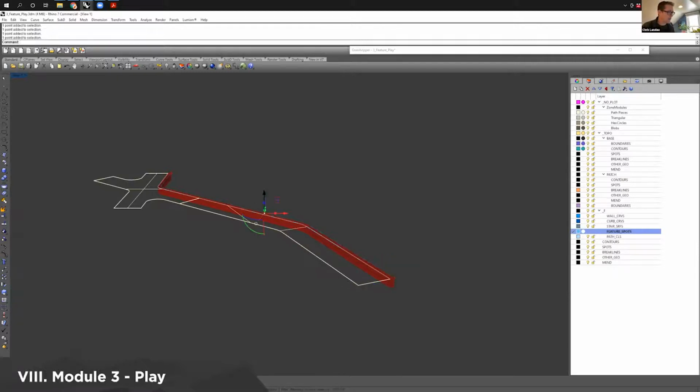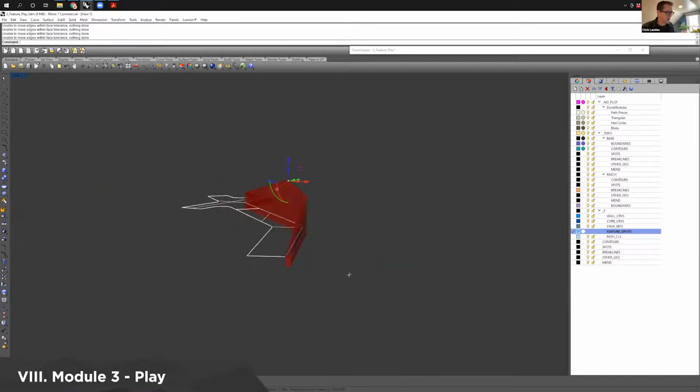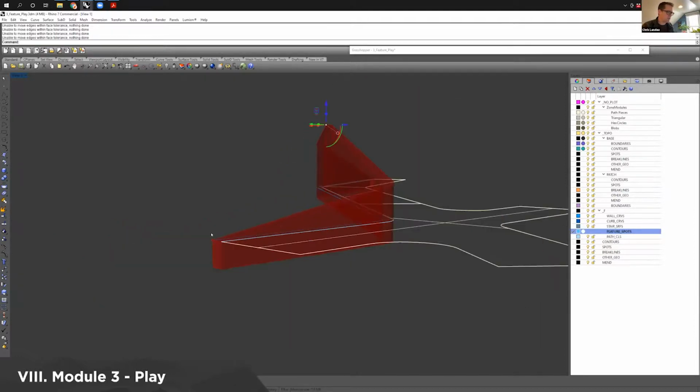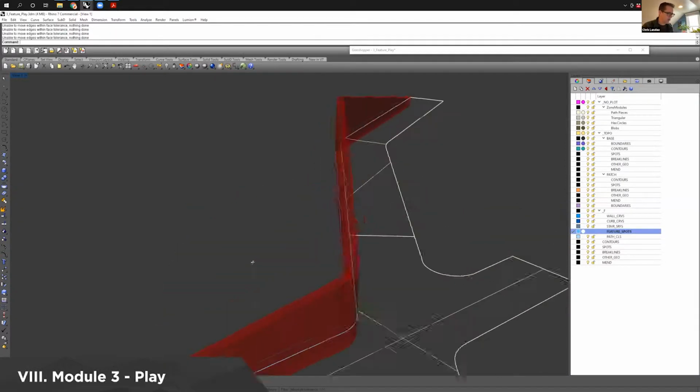And I can take this and raise this up. And now my wall interpolates between this spot and this spot for the top. So you always have to think top, back, bottom, front, right? And then, okay, so maybe this doesn't come all the way down and it comes up to here, or maybe we say 1.5,